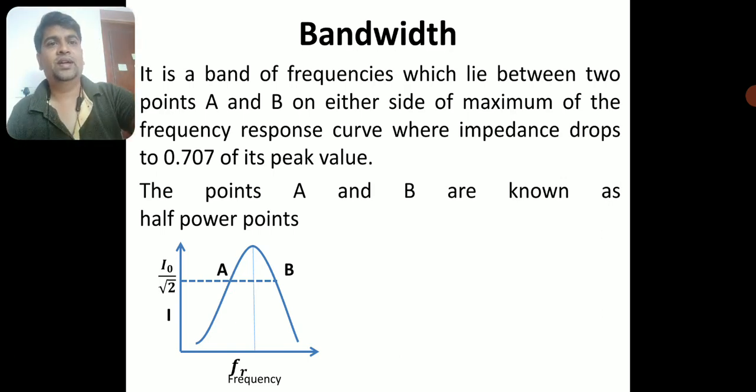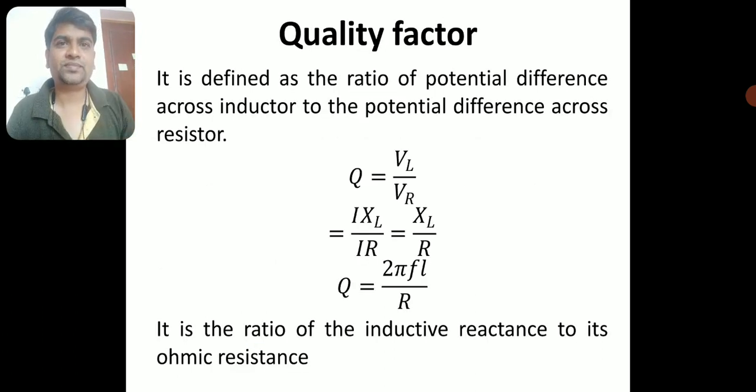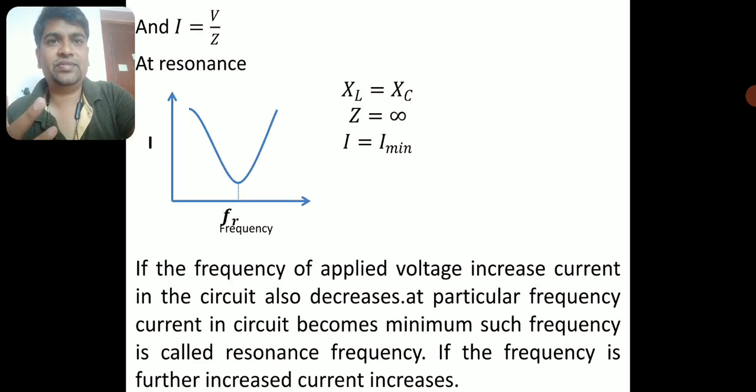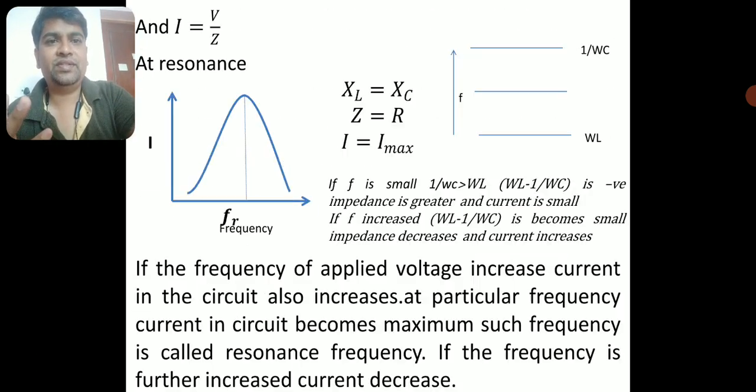Okay, right. But if you increase or decrease the resistance, will that change the resonant frequency? No, I'll say no. If you increase or decrease the resistance in a series LCR circuit, that will not decide the resonant frequency, because of the formula for resonant frequency. I have not derived an equation for resonant frequency, which is a very simple thing.